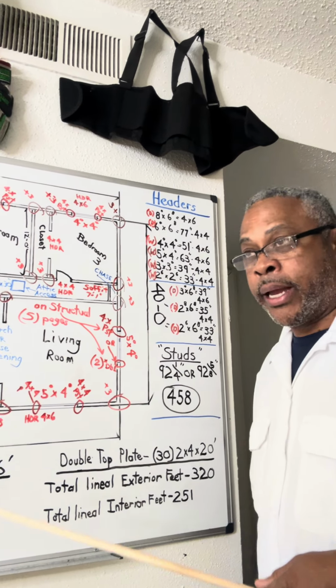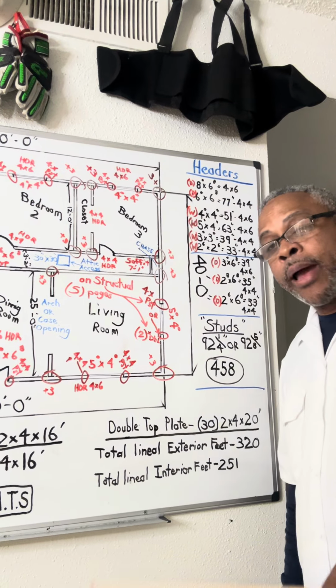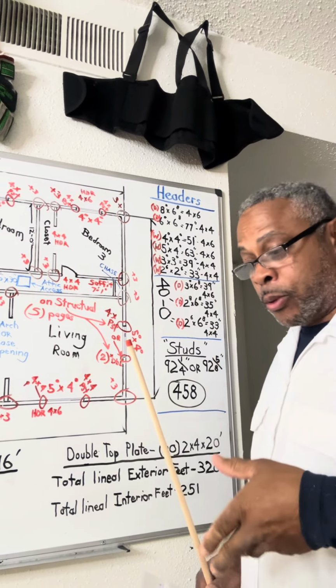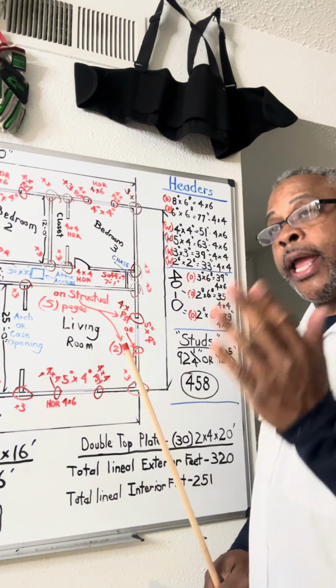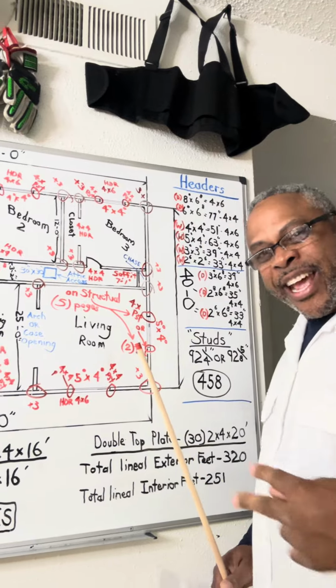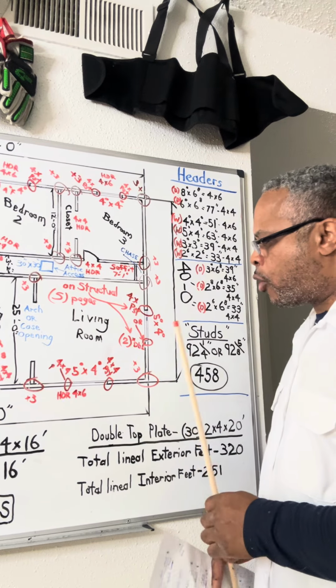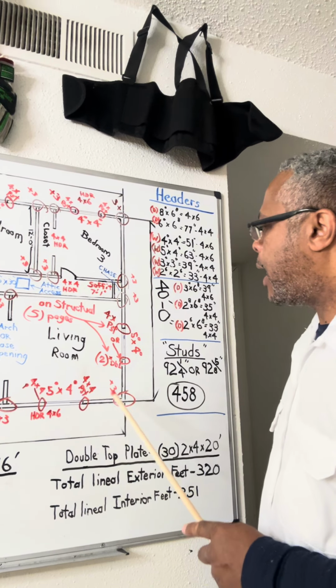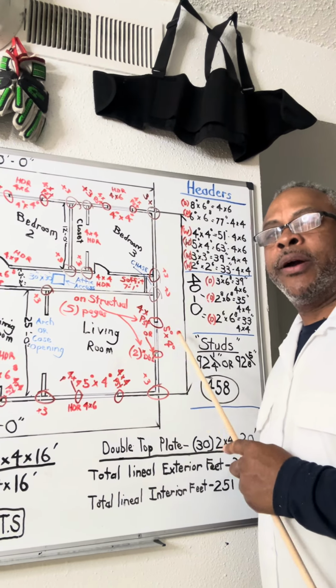I've seen four king studs nailed up, and it's because of the engineering of that building. He had a PHD strap from the concrete strapping to that, embedded into the foundation. It bends back over and nails right into that 4x4 for this window. I have a 504 window here for glazing.